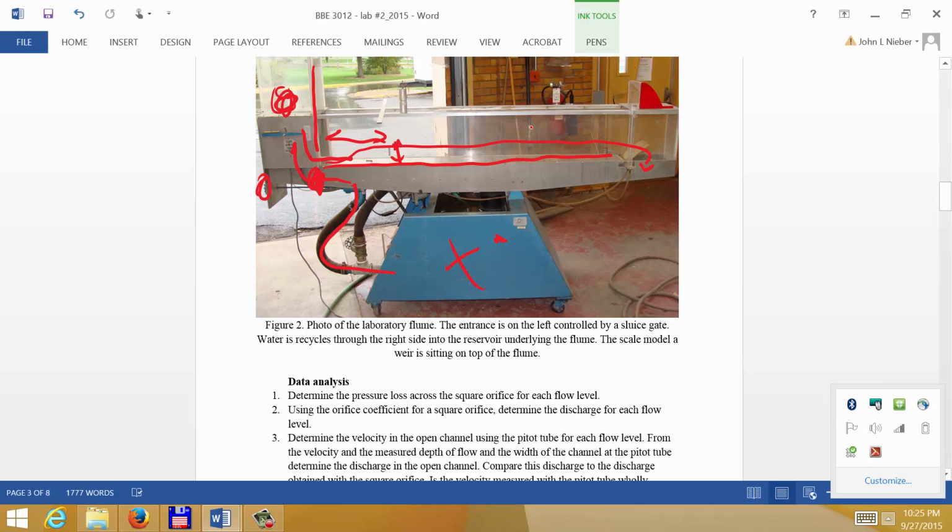You'll know then what the depth of water is, and I know that what you'll see is that the water is going to be fluctuating up and down. The depth will be because of turbulence and so on, but you should try to approximate the height of that water surface, somewhat of an average depth for that water surface at any given location, but you'll have 5 measurements of that water level.